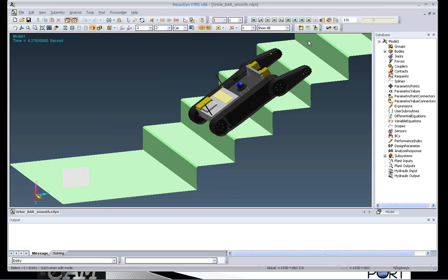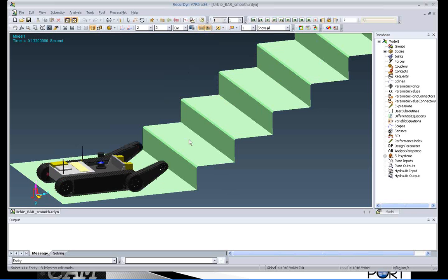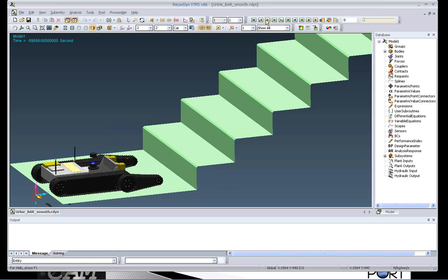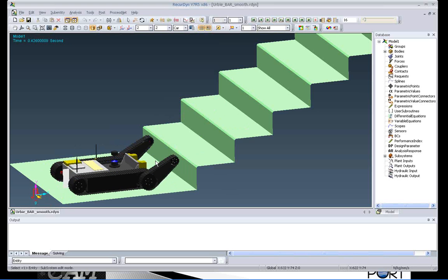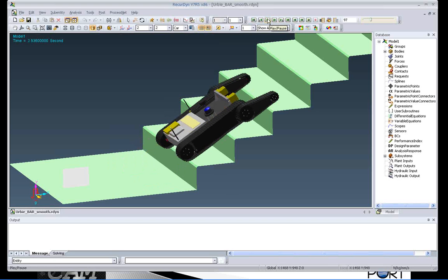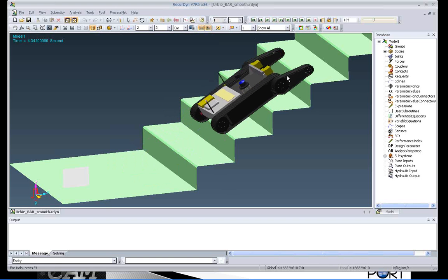So this is the sequence: with FEMAP, you need to have accurate loads in order to get accurate outputs. And in order to get accurate loads, you can use this kind of simulation, or you can obtain data from tests. But from a best practice point of view, the recommended way is actually to use both simulation and test. In other words, when you have a product like this, and maybe it only exists at the very beginning as a concept, then your only source of estimated loads would be from the simulation.